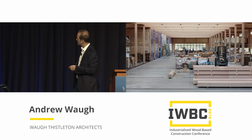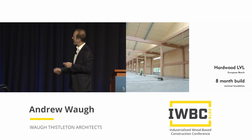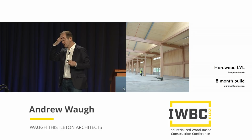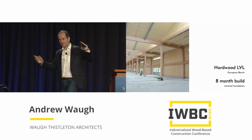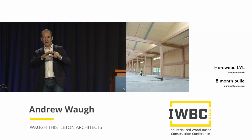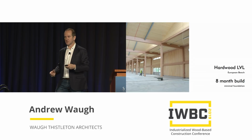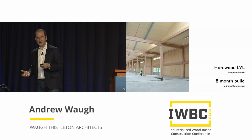These are spare beams. So when the client wants to put in a mezzanine here, or to change the floor configuration, they can slot these beams into the columns here and build new floors. That span is a little over 75 feet, and the depth of the beam is less than 2 feet. So you're getting a beam strength in terms of its actual size which is equivalent to steel, but you don't have to fire protect it.